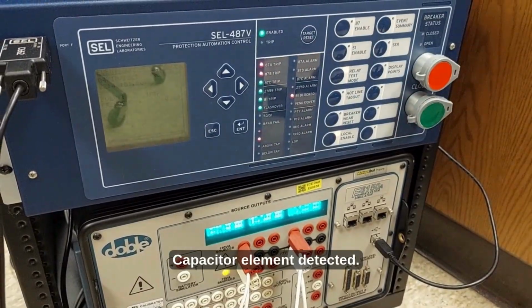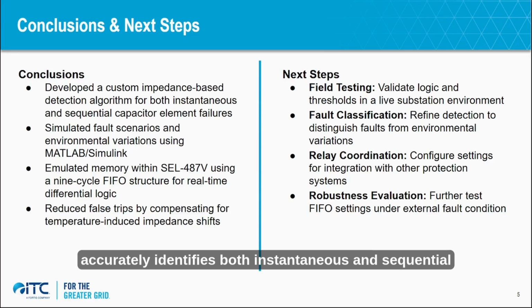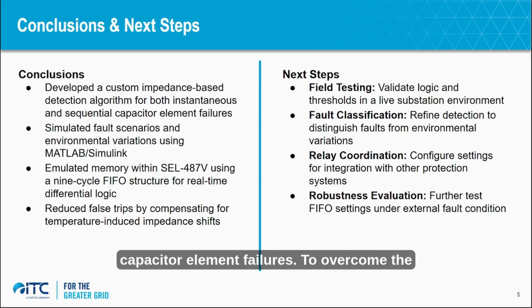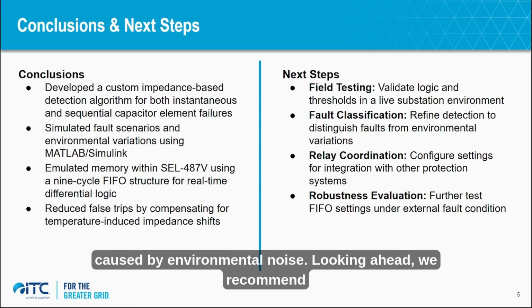Capacitor element detected. In summary, we developed and validated an impedance-based detection algorithm. It accurately identifies both instantaneous and sequential capacitor element failures. To overcome the SEL 487V's memory limitations, we implemented a 9-cycle FIFO structure. This allowed for real-time differential logic and significantly improved fault detection accuracy. It also helped reduce false trips caused by environmental noise.